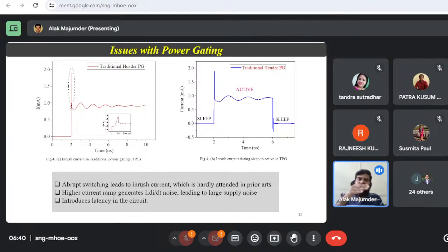So when you are inserting, the cylindrical layer of the socket and the cylindrical pins which you are inserting have an air gap between them. One metal line from the pin, another metal line from the socket, in between an air gap, they suddenly create a parallel plate capacitance. And very instantaneously, they get charged up. The moment you fix it properly, there is no capacitance.